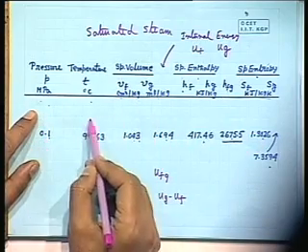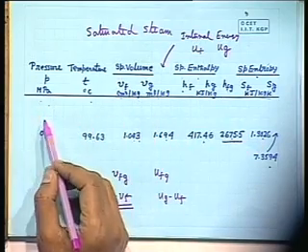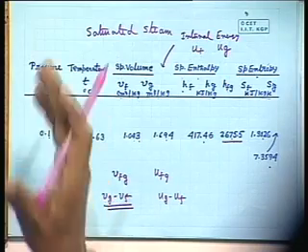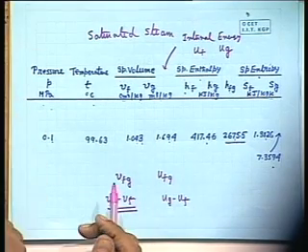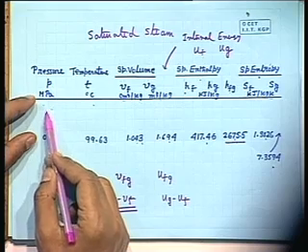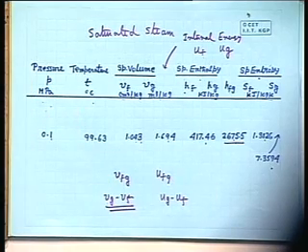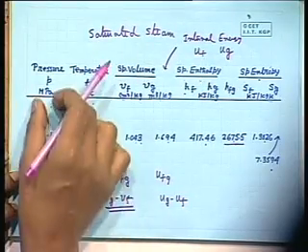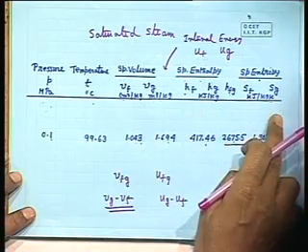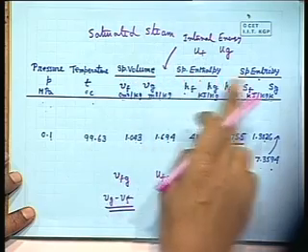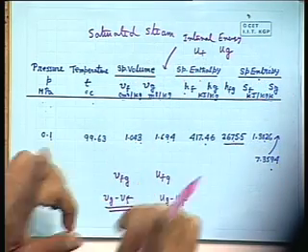Sometimes you require properties at some temperature, so you have to find the saturation pressure, then you see the temperature table. If I tell you that water and steam at 150 degrees Celsius are coexisting in equilibrium, in a pressure table you may not have 150 degrees Celsius, so you have to interpolate. So you see the temperature-wise table, where you will find 150 degrees Celsius. The resolution between two pressures and temperatures is usually 20 degrees, 50 degrees, depending upon the table. Okay, clear? So on the left side is pressure or temperature, with the corresponding saturation temperature or saturation pressure, and all the values of specific volume, specific enthalpy, specific entropy for two endpoints, that means two saturated states.